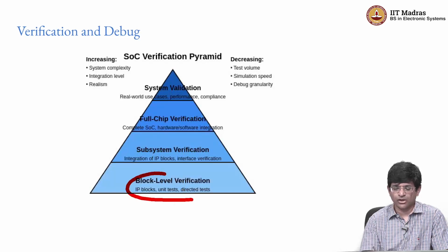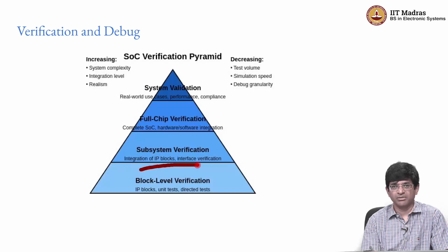But once we have verified that our individual blocks, let's say adders, multipliers and so on, have been verified and tested properly, we can start to integrate them maybe into ALUs or some subcomponents, right, and start to do basic integration and some level of interface verification.